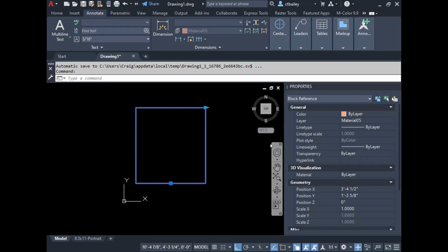Select a parameter. Which one do you want it to? So when the width moves, that will move too. That's right, so pick the width parameter. So select it that way. Now pick the second one. Watch your command line. Click it. See how the red thing is highlighted?